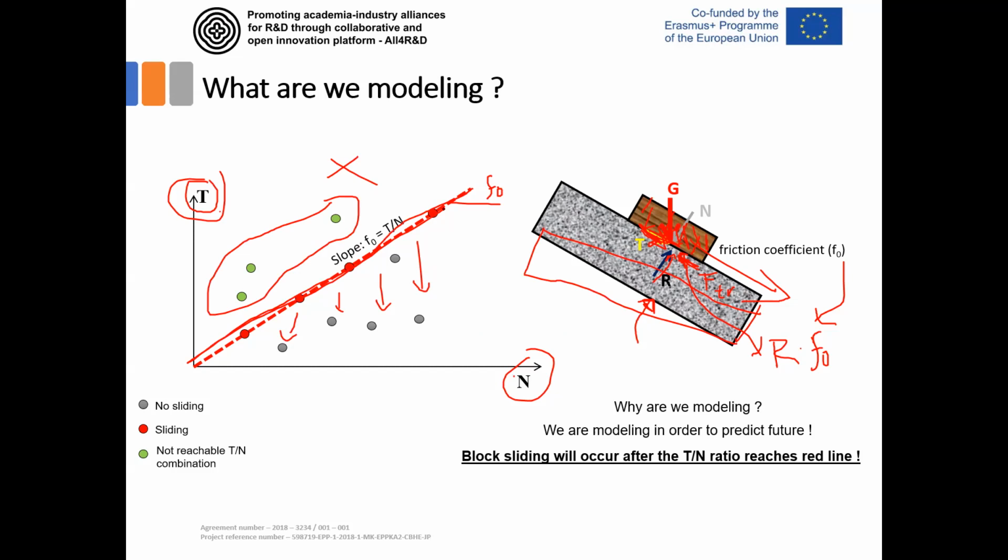Well, that's exactly what happens in a landslide when you don't have stiff elements like here, but you have a slope that is sliding like this. But still you have some element with its self weight, and we have some reaction here. There's a friction force that is supporting the soil mass, and the component of this weight is this attack force that's trying to move this landslide down the hill.